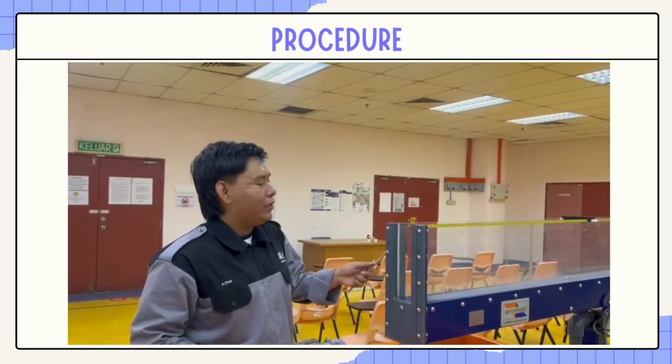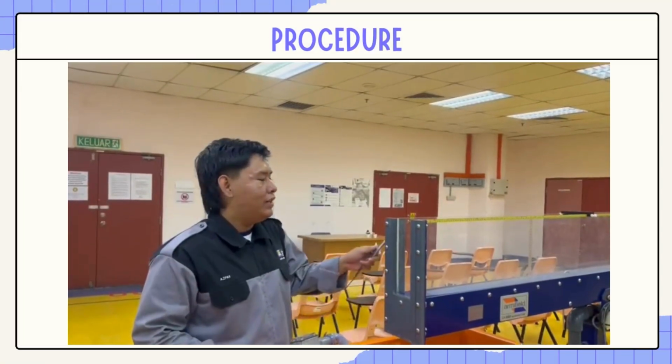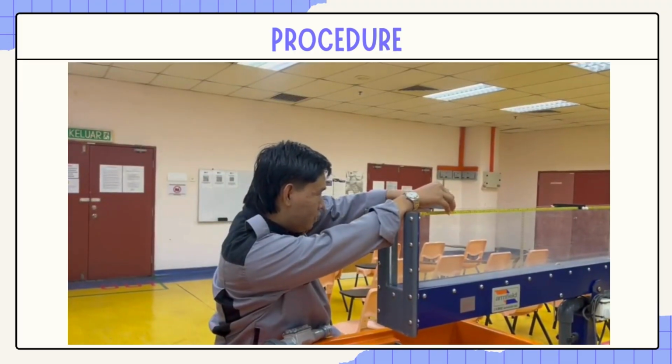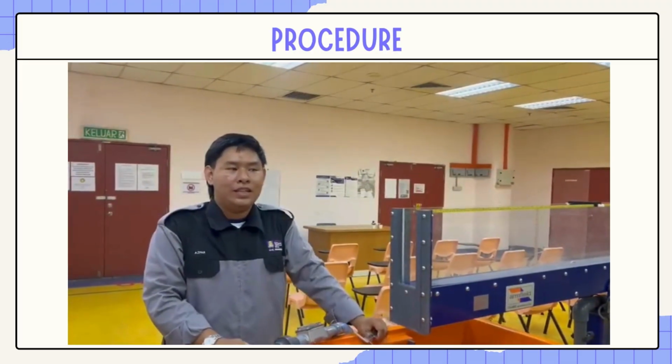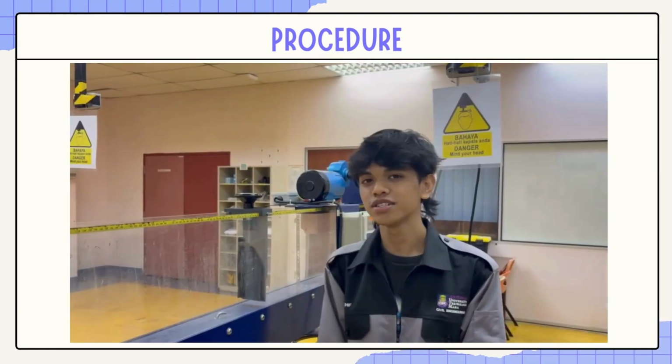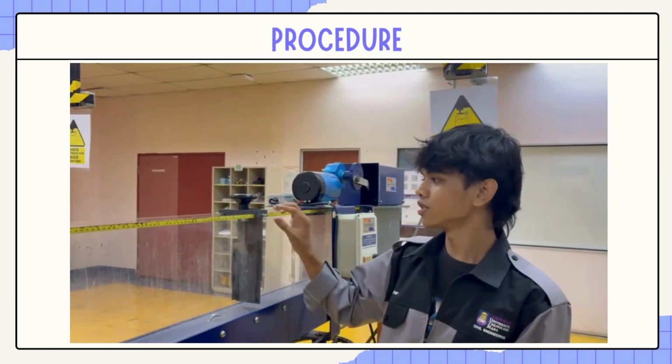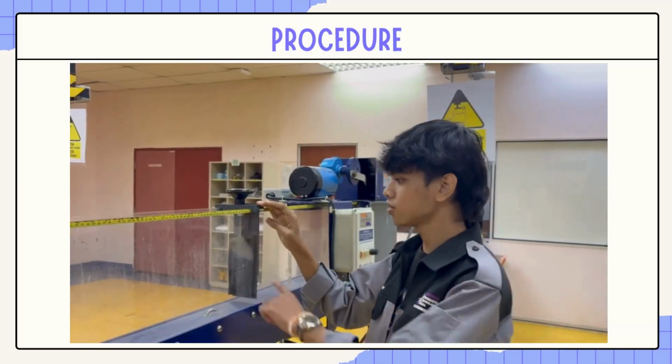Okay, the first step to conduct this experiment is we must measure the width of the rectangular upper channel. So the width of the rectangular upper channel is 7.7 cm. Okay, first we measure the height of the sluice gate and the opening is 10 mm. After that we tighten the sluice gate so that the water doesn't push it.